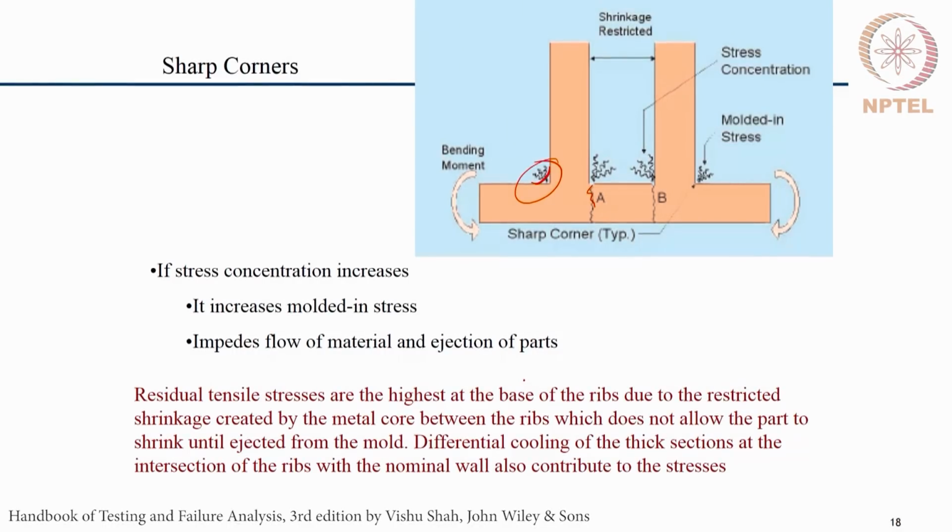At these points we have what we call molded-in stress, because the material has resistance in flowing at these corners, and that could also be a potential cause of failure because of the forces involved in ejecting this component.